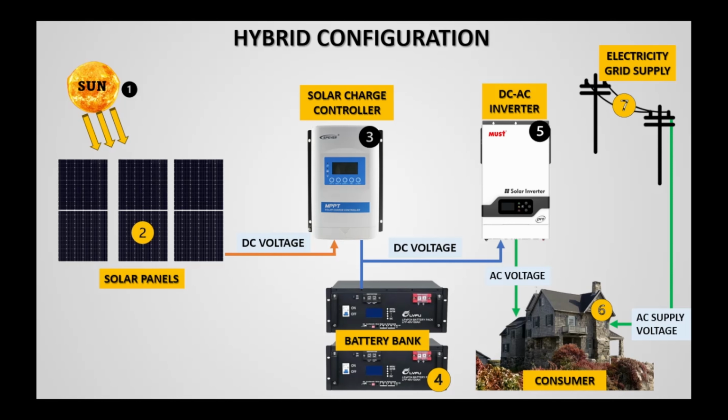The only downfall of an off-grid system is that it costs a lot to have a bigger battery bank as well as solar arrays, whereas in a hybrid system you can still get away with a system that can last maybe a day or two, because you still have the supply from your electricity system.